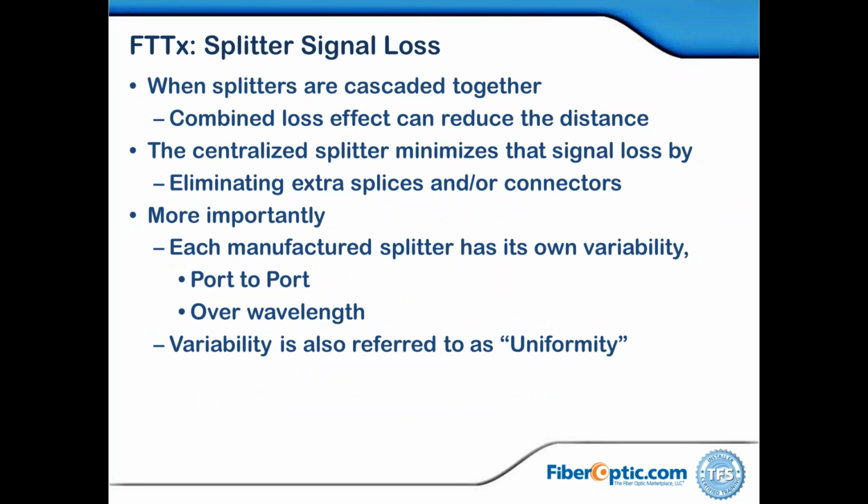Now, when you look at the budget losses through a splitter, it's some pretty basic stuff. You may have had some of this in basic electronics, but we're going to have pretty high losses in this physical plant. Unlike what we normally think of on a pole for normal telephony, our losses are going to be pretty substantial. And it comes from the fact that the splitters are passive and they split the signal. This is not unlike a typical cable TV coaxial or RF splitter. In fact, all of the light still follows the 3 dB rule of power, which means every change of 3 dB you double or halve.